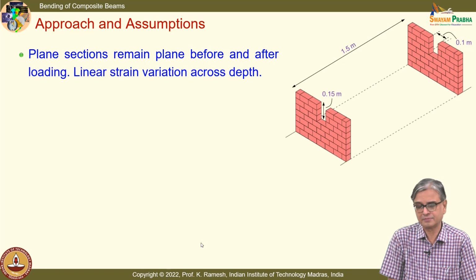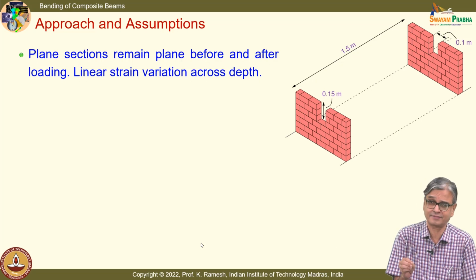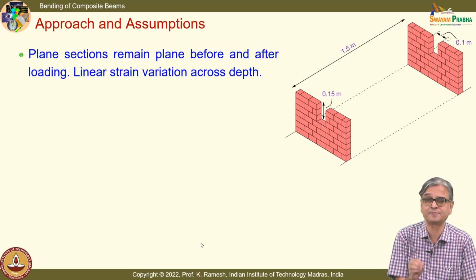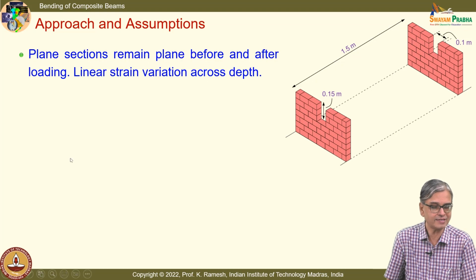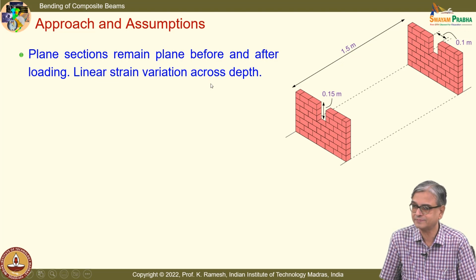And I am obviously going to have a heterogeneous material. We are not studying a heterogeneous material from our analysis. We have just simply said a homogeneous material. So, we will simply close our eyes and say concrete is homogeneous. We will say plane sections remain plane before and after loading, and linear strain variation exists across the depth. This is an assumption,